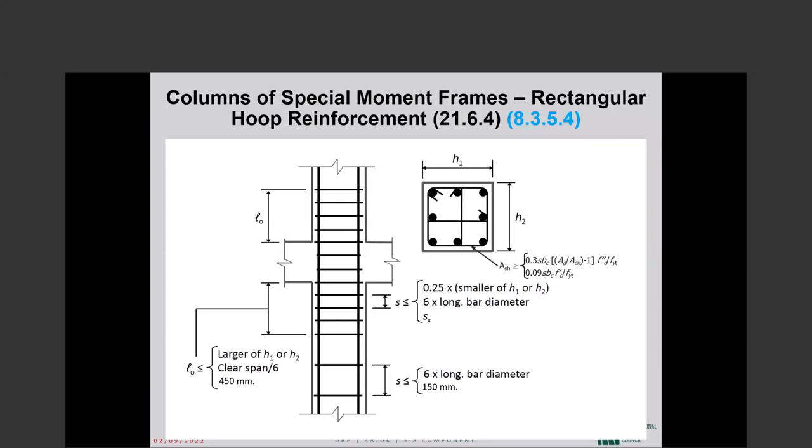The only way to get around this is if, as f'c increases, we can also increase fyt, the yield strength of the transverse reinforcement. This is why the 100 ksi limit on transverse reinforcement is so important. Okay, that allows us to use high strength concrete in columns, which is quite often highly desirable.